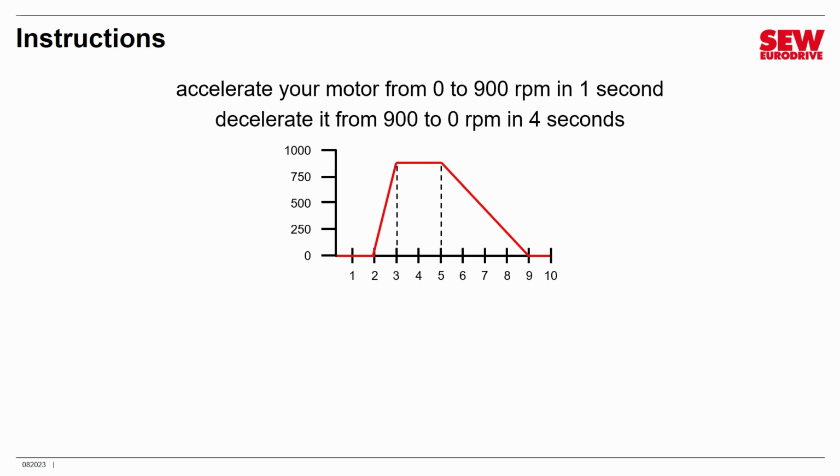So you're going to have to calculate 2 ramps and then go to those parameters, P03 and P04, and put in those numbers. Now, you may be wondering, how can you test this to make sure you're getting the times you want? Well, let me give you a handy tip on how to do a little testing.